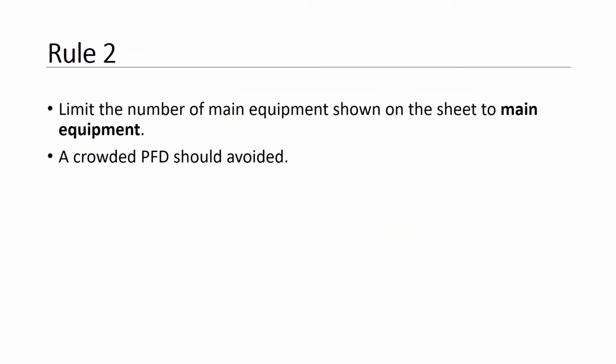Rule number 2. Limit the number of main equipment you are showing on your sheet. Stick to the main equipment. Avoid crowding or overcrowding your PFD. A PFD should be simple and easy to understand. You should be able to follow the streams.